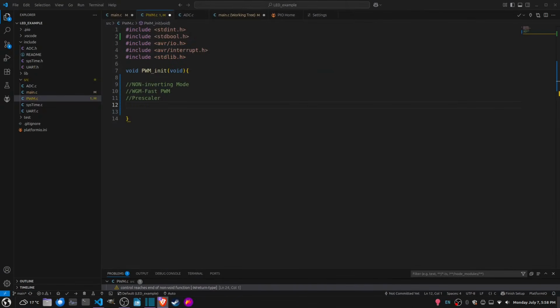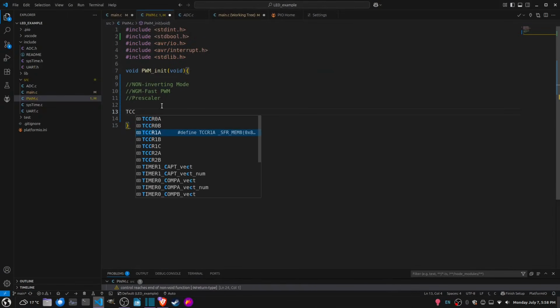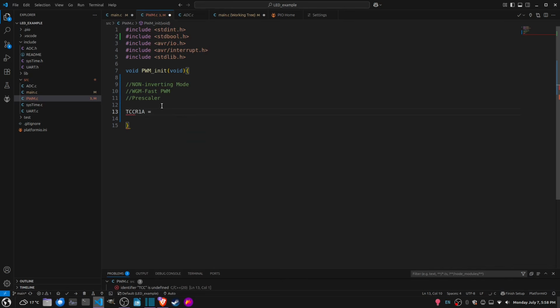So we'll bring this to the side and access this register, and then set that bit to high. So that's all. All we've done is set non-inverting mode. That's complete. The next one is our WGM, and we have to place it in fast PWM mode.